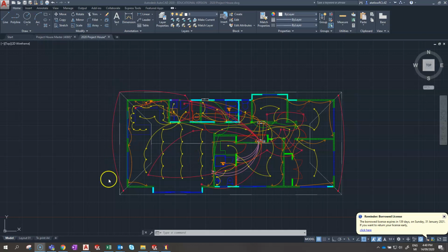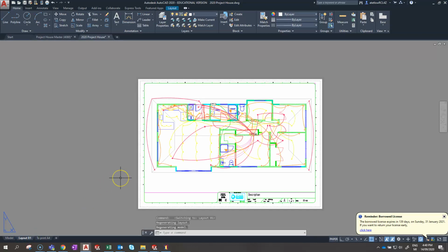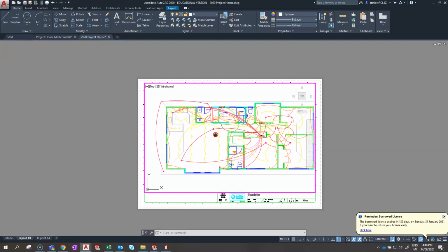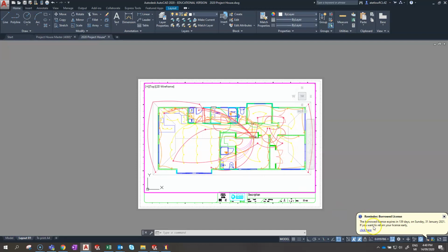So our template should already have one layout. And so if we go to that layout, and it depends on what yours looks like, but this is at the moment in paper space. And my viewport is normal, it's not highlighted. If I click on the word paper, it'll change to model. This is now highlighted. I'm now working with the information from model space through my viewport window. So we want to line it up where it should be, and then we want to choose an accurate scale.